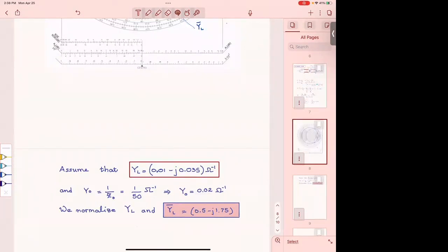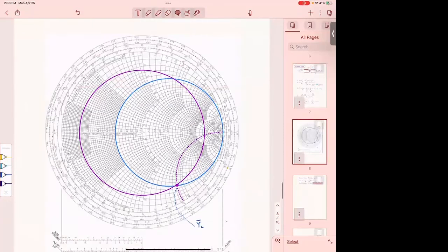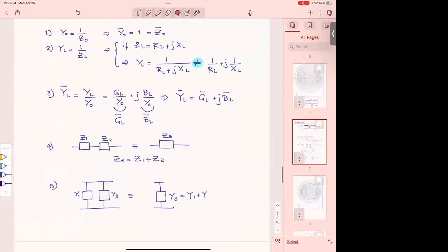Yes. First of all, you have to decide how you are going to split the real and imaginary parts, into conductances or resistive conductances, and then the inductor or capacitor. You have to remember what a plus means in admittances. When do we sum up two admittances? When they are in parallel. All right, remember that.